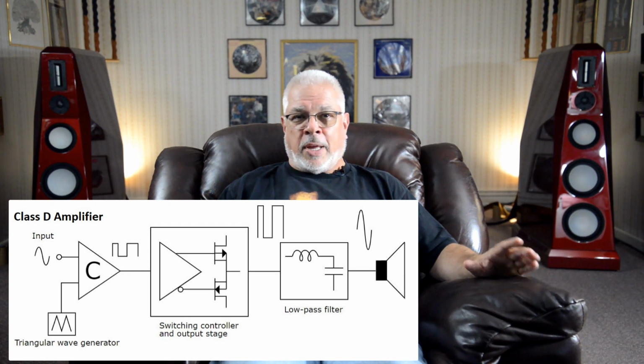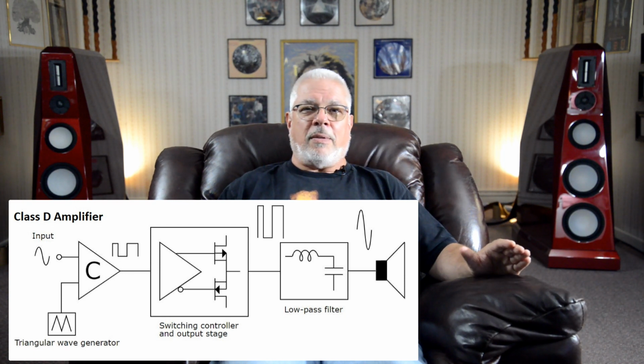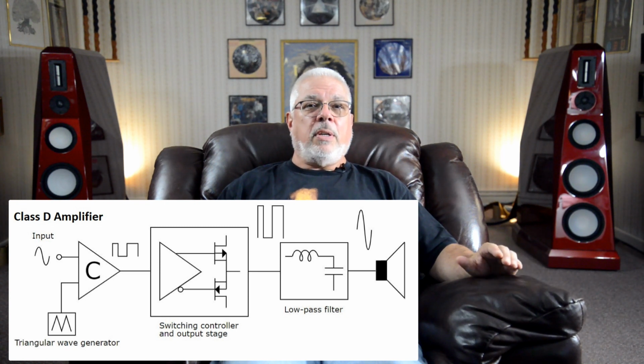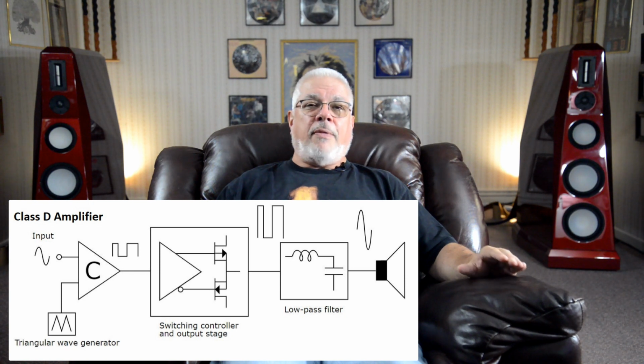The analog signal is converted to a stream of pulses that represents the signal by pulse width modulation, pulse density modulation, or delta sigma modulation, or some related modulation technique, to constantly switch the signal between fully on and fully off, driving the output into the transistor saturation and cutoff regions.